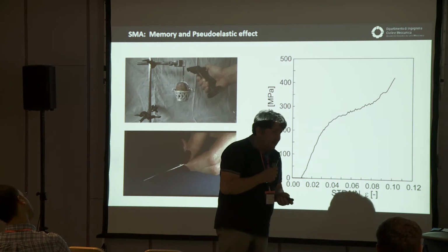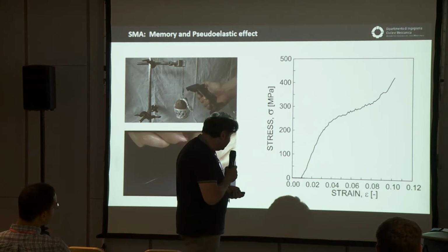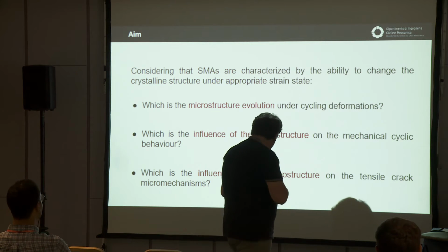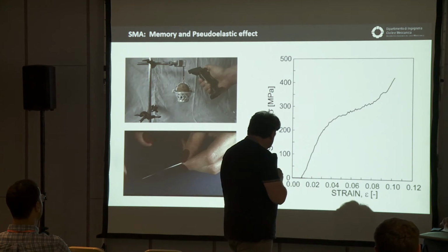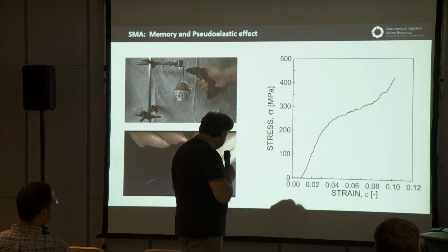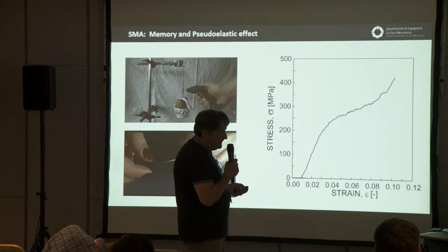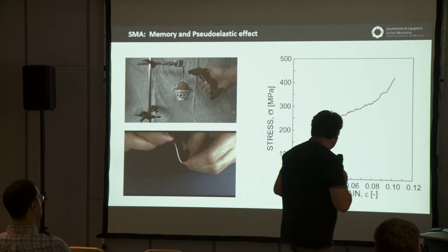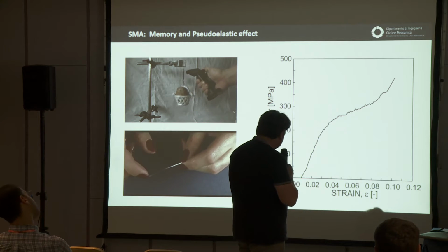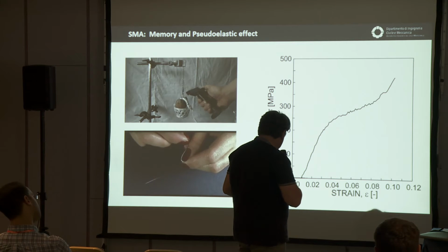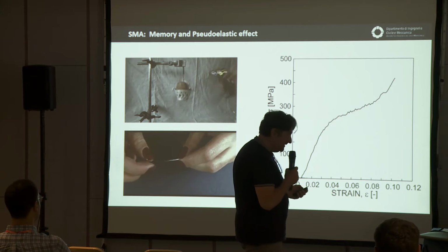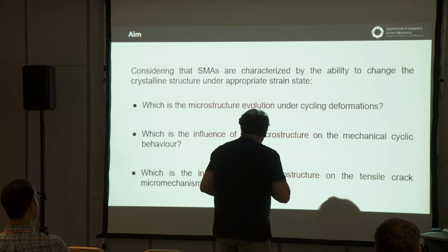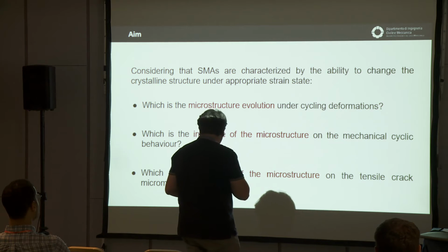perform some kinds of test. The first one is a simple tensile test, and you can see that the plateau is not a real plateau, because we have a sort of slope in this stage, and then we have the austenite and martensite ones. So the suspicion is that the transformation is not linear. Okay.